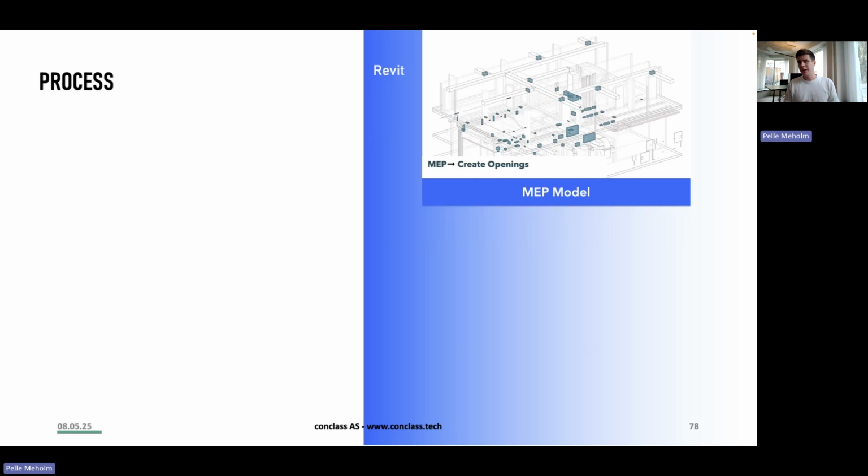Usually, we do not recommend creating the openings in the MEP model if you are working in a large-scale project. So in case you have a huge project with more than 1,000 openings, it's recommended to use a separate file just to create, update, and coordinate the openings instead of having all the openings in your MEP model. But of course, all scenarios are possible, and today we will show you one possible scenario. All right, René, you are free to share your screen.